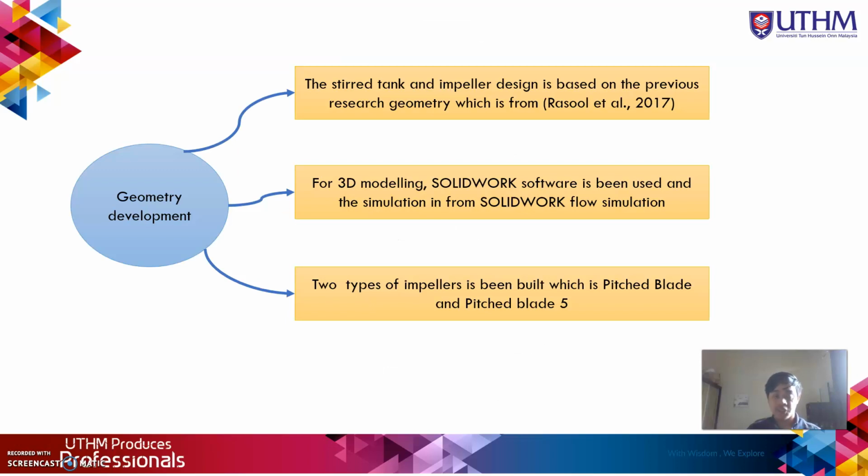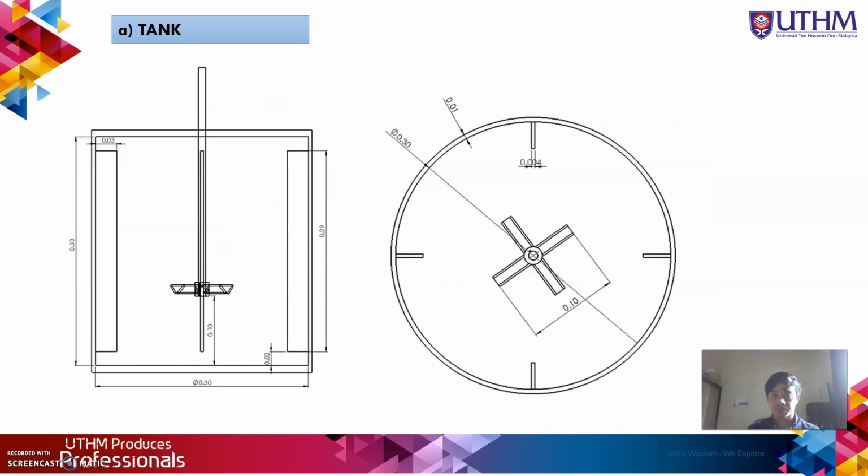Okay, next is the geometry development. The steel tank and the impeller design is based on the previous research geometry, which is from Russell 2017. For 3D modeling, I have used the SolidWorks software to build the impeller and the steel tank design. For the simulation, I will use the SolidWorks flow simulation. Two types of impeller are being built, which is pitch blade and pitch blade 5.